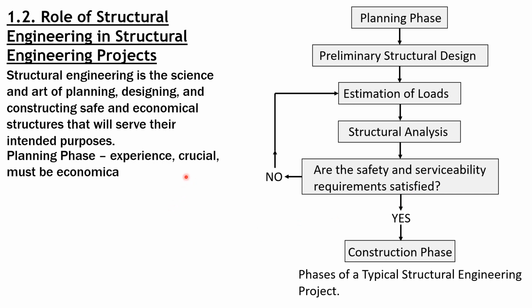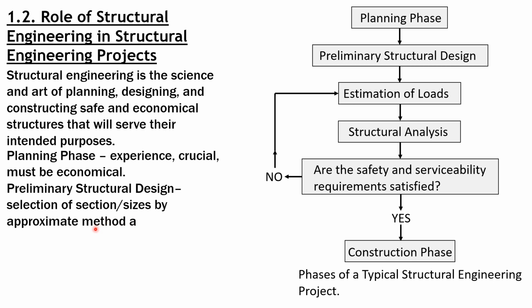In the planning phase, you need the experience of people who are already structural engineers. This is very crucial, especially in the selection of materials and the type of construction procedures that must be applied in a certain structural project. Aside from safety, then preliminary structural design consists of selection of section sizes by approximate method and experience.